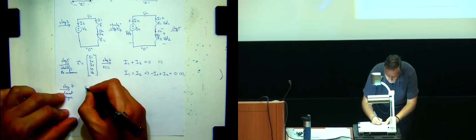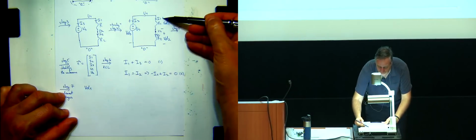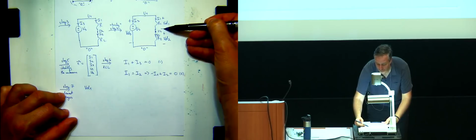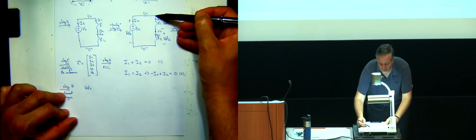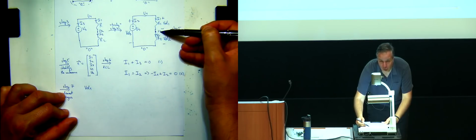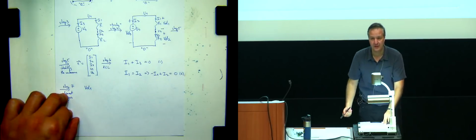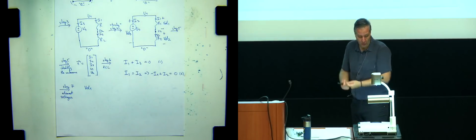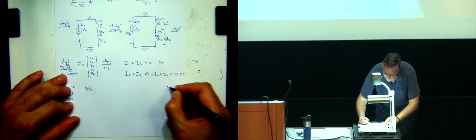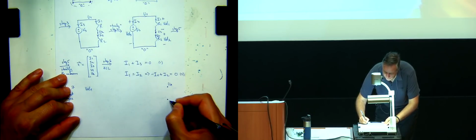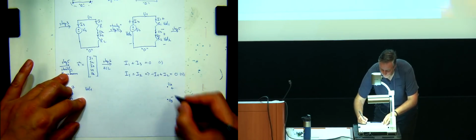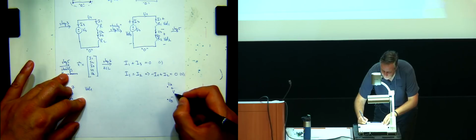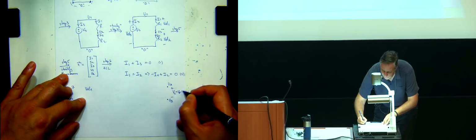So let's say for V element 1. V element 1 is here. Right. On one end is U1. That's the potential here. On the other end is U2. That's the potential where my minus sign is. A definition of the voltage, and let's maybe do it here on the side just so people know. If I have potential UA and UB, and I label my voltage here like this, let's call it VC, that is equal to UA minus UB.